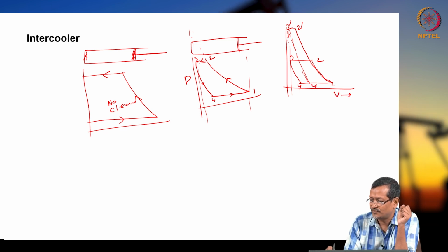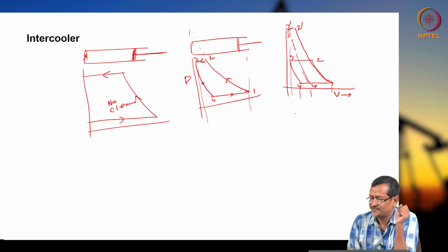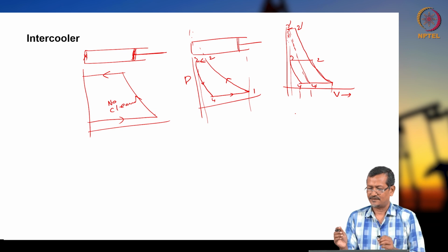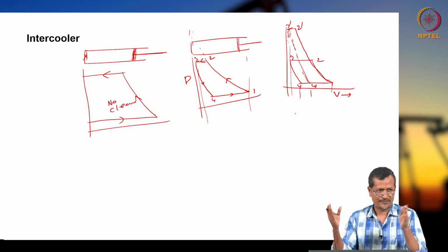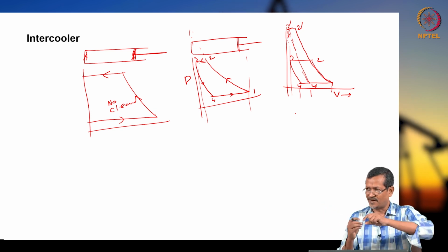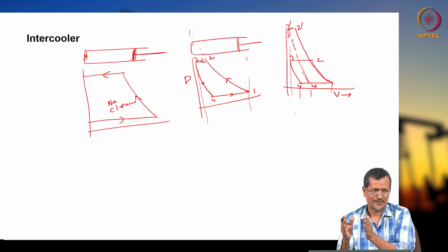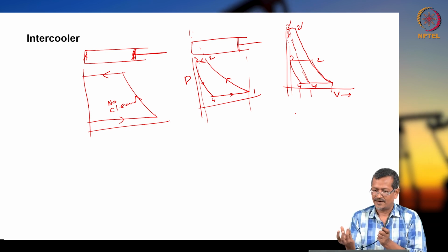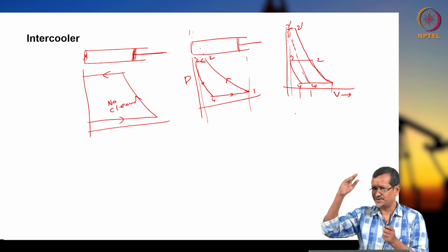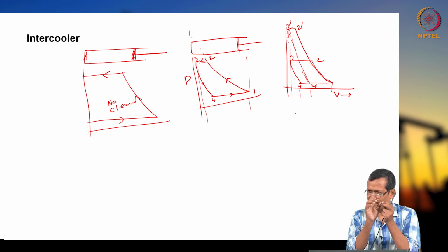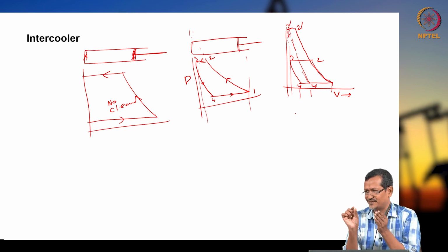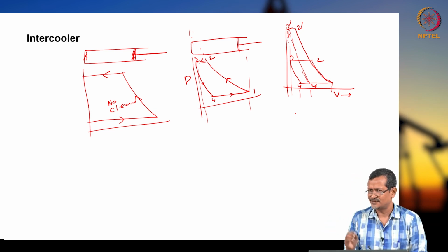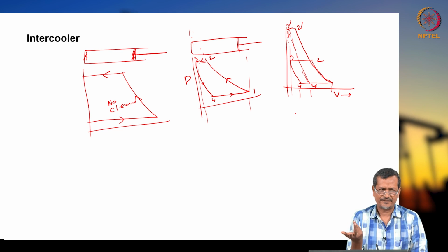So V you see V changed, so the intake total amount is changed. Okay, initially you had air 1 to 4, that volume you are sucking, right, but because of very high compression ratio you are sucking a small amount, that means the total amount of fluid delivery will be low. Okay, so if you increase air pressure further, the compressed gas part will be expanding further, so intake will be very low. So if you increase it to as much as 100 psi, in that case intake will be so low, it will not be effective.